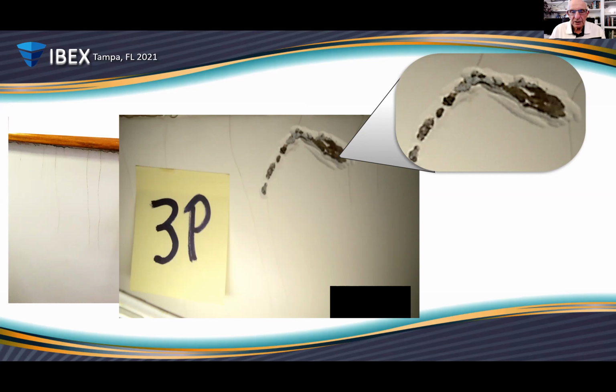And this is an extreme example. But if the spec on the gel coat is 18 to 24 mils, and say the gel coater doubles up in corners, for example. So they spray the proper 18 mils in a flat and in the corner, and then they spray the next panel down into the corner. They might have 18 mils and 18 mils and 36 mils in the corner. It might not look too much different than this if the spraying techniques aren't refined enough to produce the same thickness of gel coat in those overlapping areas. So you need to be careful about thickness buildup in tight places.